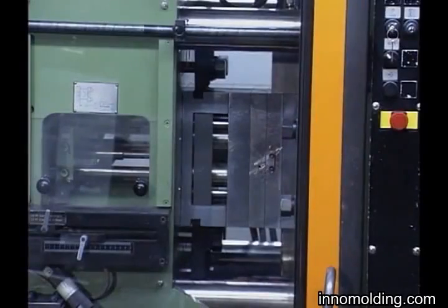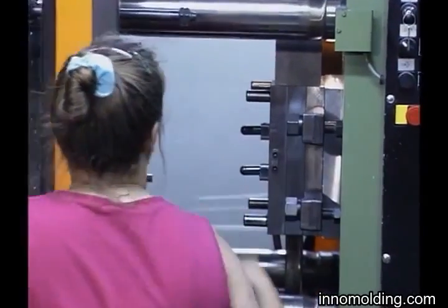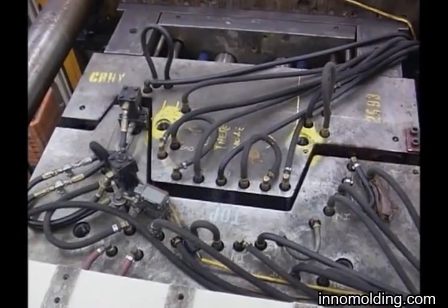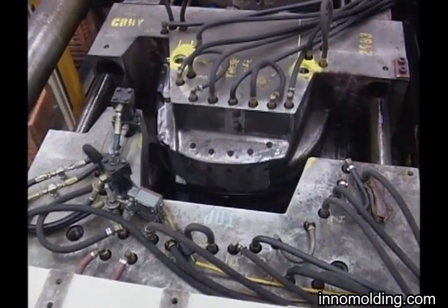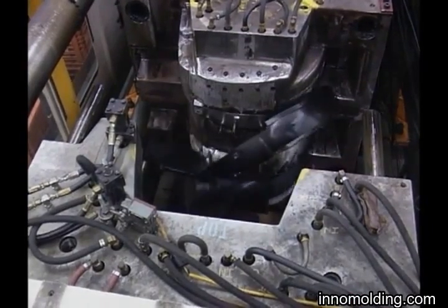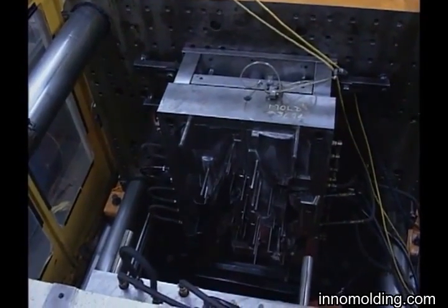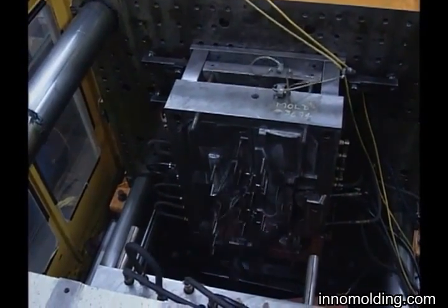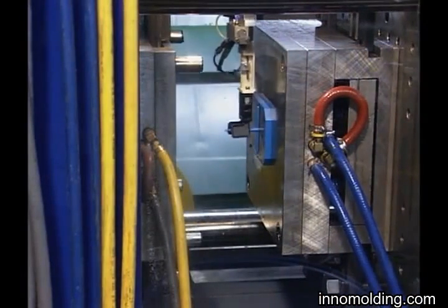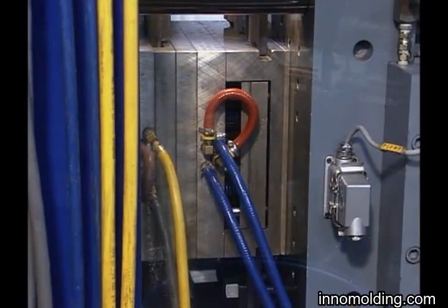Once the part has had time to cool and solidify, the mold opens at the parting line, which may be flat or irregular. Since the force of the molten plastic against the mold creates significant friction, a knockout system is required to aid in part ejection. This is usually in the form of knockout pins. In some molds, a sprue puller aids in removing the molded plastic from the sprue. This material can then be reground for reuse.